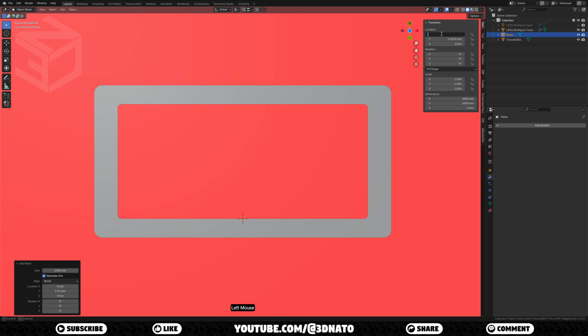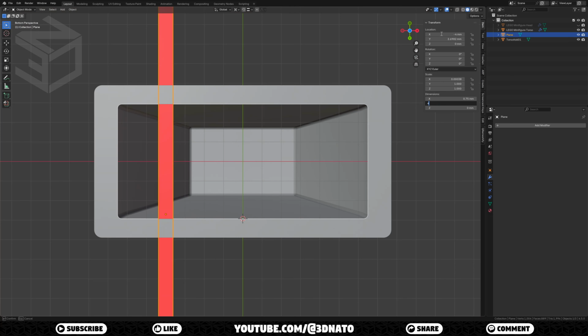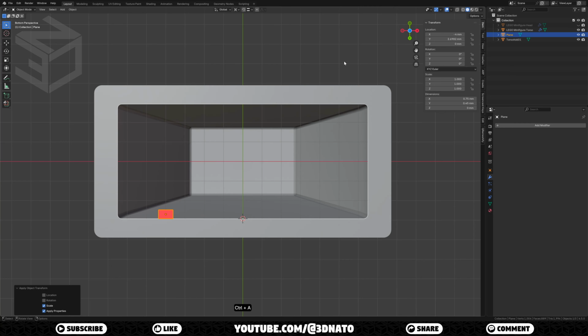Set the X location to -4mm, and on the Y location, subtract 0.45 divided by 2 from the current value. On dimensions, set X to 0.75mm and Y to 0.45mm. Now press Ctrl+A and apply scale.